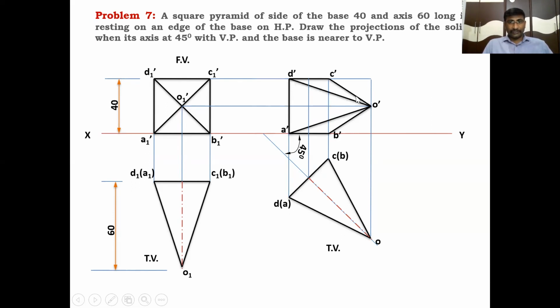A dash O and D dash O are visible slant edges, which are dark lines. Okay, we already drew C dash O and D dash O, which are outer sides, and the invisible line is C dash, B dash. Clear? Because it is away from the observer, being nearer to the XY line.